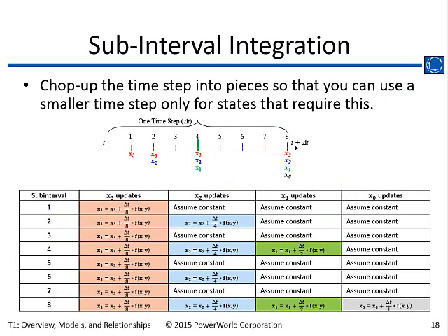Something that's a little subtle is that a lot of times when we study systems, particularly with exciters in them, sometimes with stabilizers, that quarter cycle time step is too large for the dynamics going on in the exciter or stabilizer, or sometimes within induction machines. So we have to do what's called sub-interval integration. We take the integration for these models and make it even more fine than a quarter cycle. This is what we call sub-interval integration.